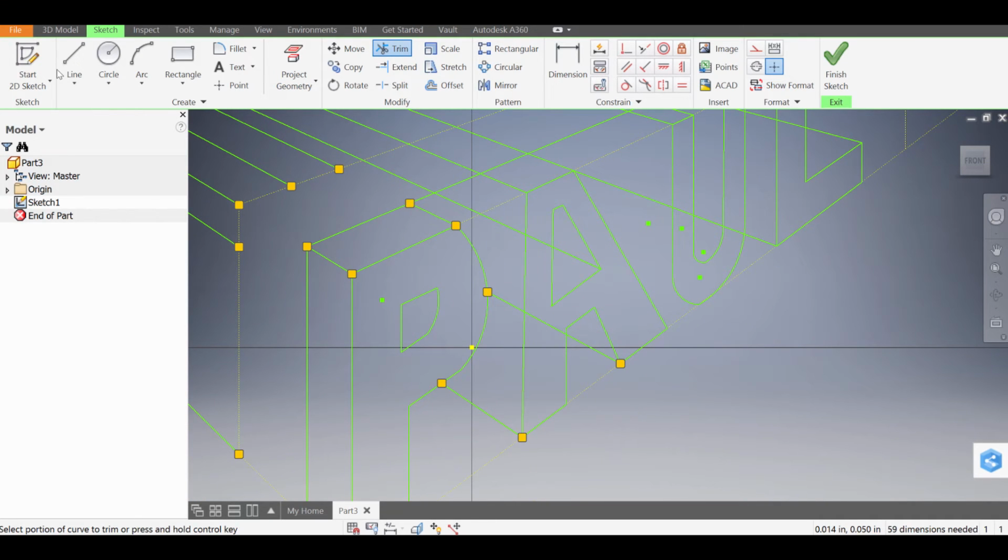Something with the A, and something I'd recommend: let's say I drew a line, because I need to match that angle, but this works with anything. If I drew a line like this, and I'm not sure if it matches this line, they don't look parallel, what I'd recommend doing is selecting the line that I don't want to move and putting a lock on it.